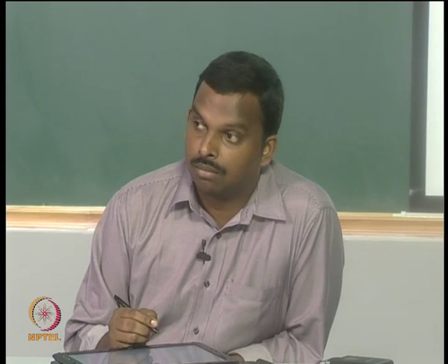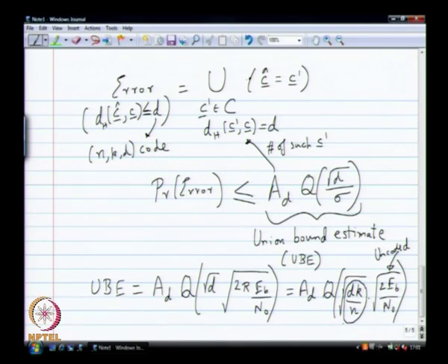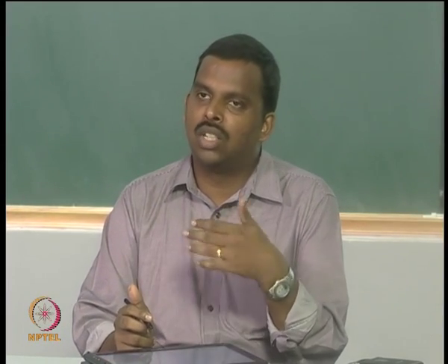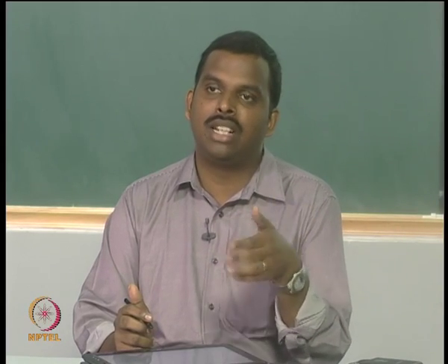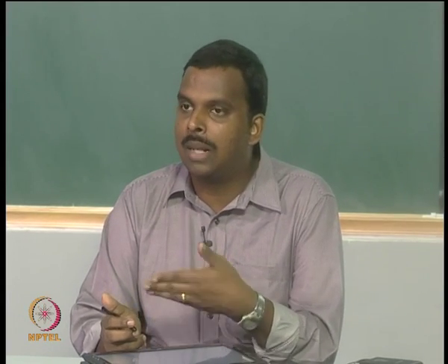Right? Yes or no? Think about it. Okay. So, this simply becomes the coding gain according to the union bound estimate, very rough estimate, but nevertheless it is a good thing to have. What it particularly brings out, in my opinion at least, is the ultimate dependence on minimum distance. You can go to BPSK AWGN, you can do the best possible soft decoder. I was commenting that actually the soft ML decoder does not have an error correcting capability in the way we defined for the BSC. But that does not mean minimum distance is not important. Minimum distance is ultimately definitely important, and even in the union bound estimate it plays a direct role in determining the coding gain.